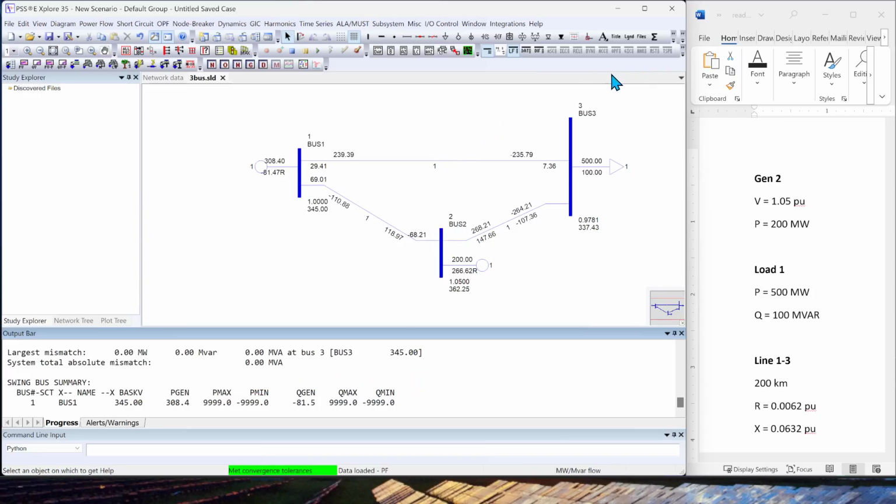Now, to enable the animations, you would see those buttons in this toolbar on the right hand side. But since I have reduced my screen size for PSSE, those got hidden in this small drop arrow. So if I click this, it will show me these options. So you should see the same symbols.